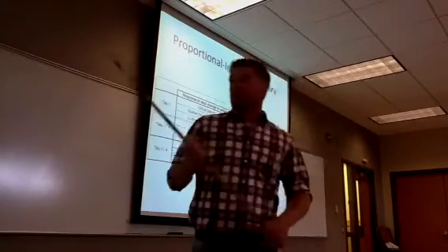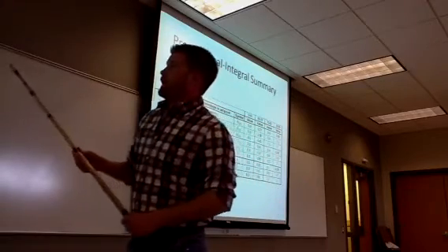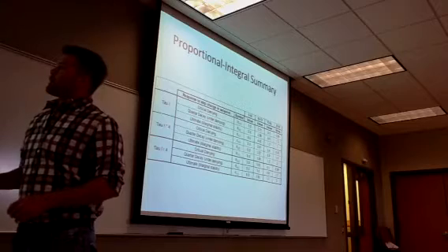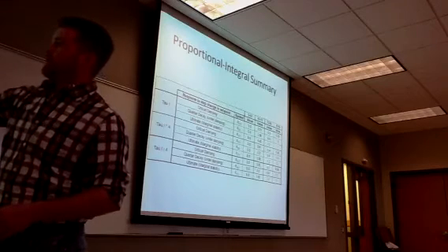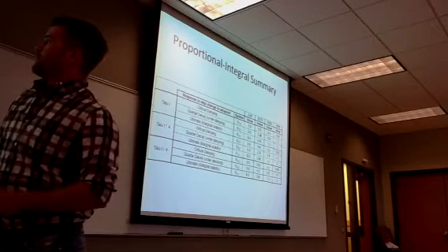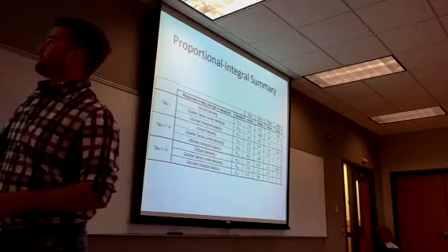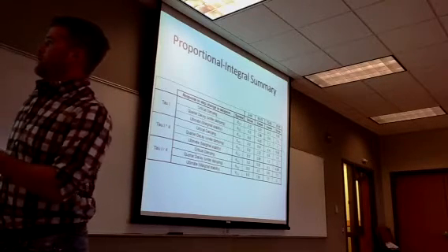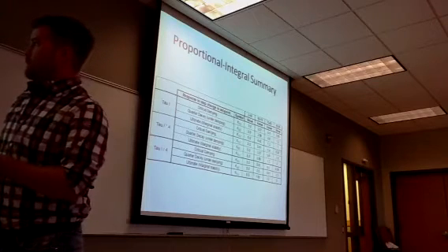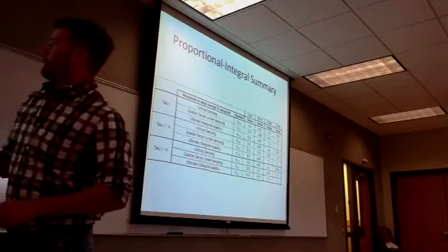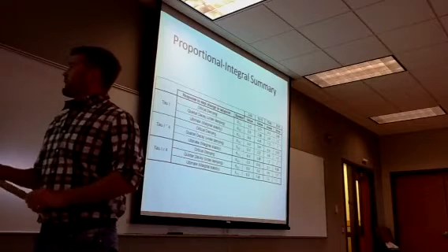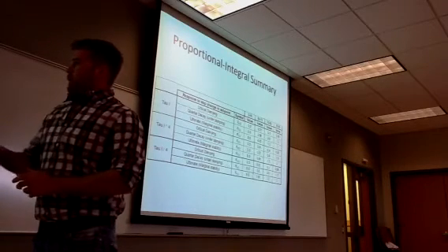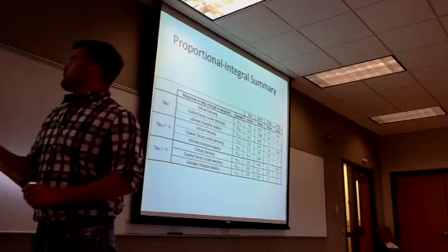And here's the summary that we have. As you can see, for each one of the tau that we used, the value stayed pretty much the same for 0 to 50 for each of the Kc's: the quarter decay and the ultimate decay. The rest of them varied quite a bit depending on what tau we used.